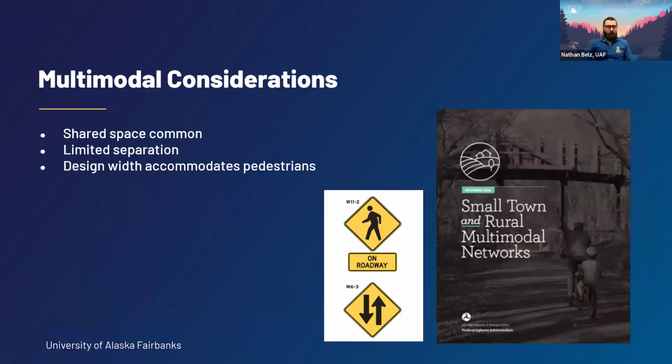As I mentioned, multimodal user considerations. Shared space is common in rural villages and communities, and oftentimes with limited separation. So not having an actual separated side or a raised sidewalk, not having a separated shared use path. So really incorporating into the roadway width and design a way to accommodate pedestrians or other users.